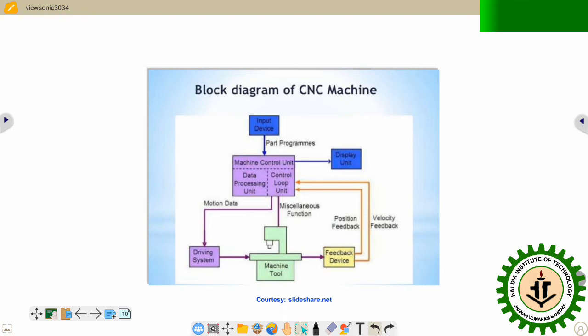This is the machine control unit. This is the heart of your CNC or NC machine tool system. All the intelligent functions, that means information processing presented in your part program, will be interpreted. Arithmetic or intermediate calculations, if required, will be taken care of by this machine control unit and implemented. Within the machine control unit, there is a partition.